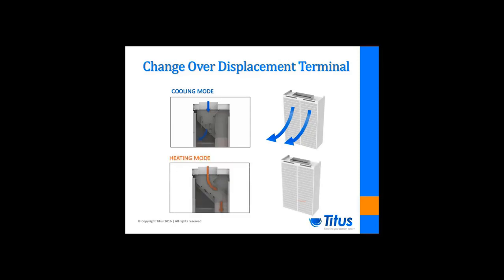During heating mode, the supply air is diverted to the smaller, lower section of the terminal and discharged with a greater velocity to increase its penetration into the space and provide more mixing with the classroom air. The Plexagon version of this terminal features light harvesting elements which provide power to the actuator to accomplish the changeover. This version requires no outside power connections and works strictly off the ambient light in the classroom itself.